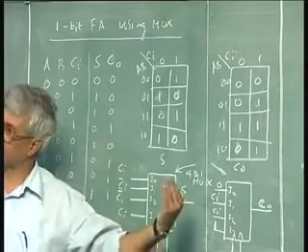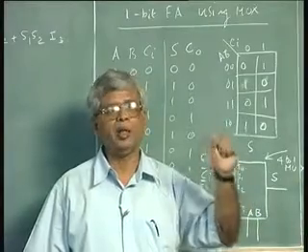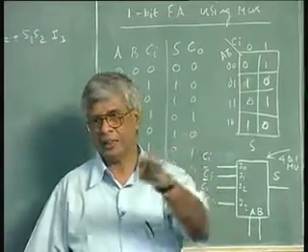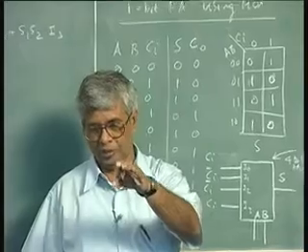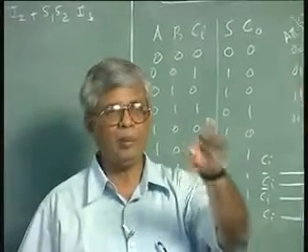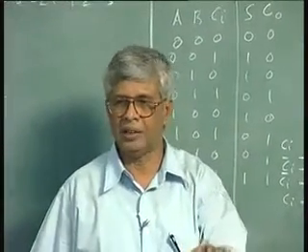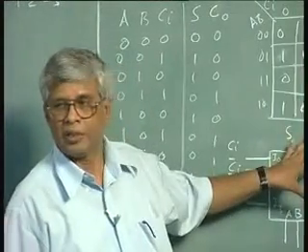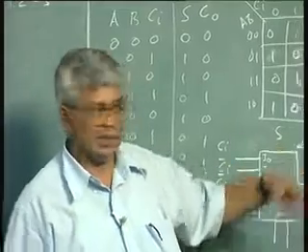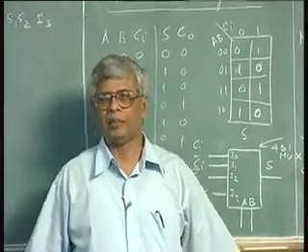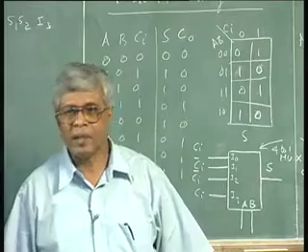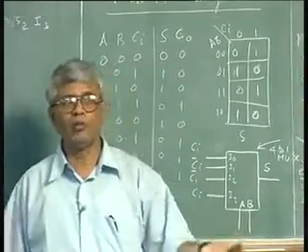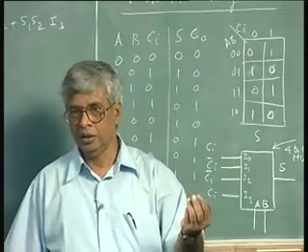I can get a decoder using other ICs also. So first thing, make an intelligent choice of the MSI. Look at the specifications of the circuit given, the specifications of the requirement. Look at the capabilities of the hardware available. Try to make a match to the extent possible. And this is a very symmetric and straightforward case. Sometimes we may have to do a little extra manipulation, and in that process we may end up with a less than efficient design, but it's worth it because we are going to reduce the total number of ICs. So this is only an example.